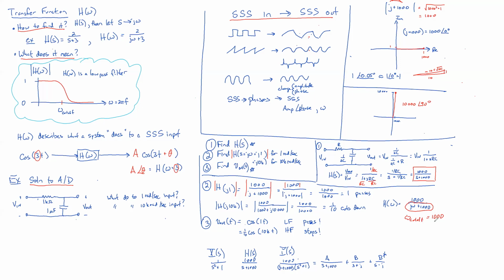My only other question is that before we solved that, this was equal to 1 over RC, which would be frequency. So would it be 1,000 times 2 pi, or would it just be 1,000 if it's an omega cutoff? How do you convert? Is your question, how do we convert the omega cutoff to a frequency cutoff in hertz? My question is, up above in step 1, we solved that it was 1 over RC, which would be equal to frequency, right? All this is in the frequency domain, that's right. So if that's frequency, if you're transferring it to omega, would you multiply by 2 pi or divide by 2 pi?